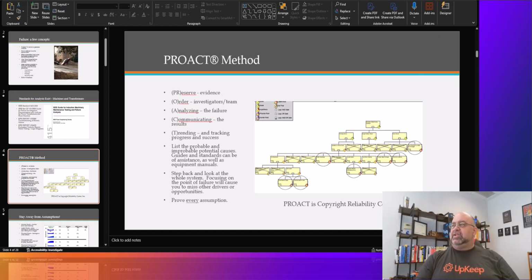So let's get into the incident at hand. This one here, if you've seen it, I call it Motor Go Boom, and you can't see the top of the page, but it is a test that was performed after field testing was performed, in which electrical signature analysis using the EMPATH identified a bunch of conditions. And we went, wow, how is this motor even running? And the vibration guys, because they were doing continuous vibration monitoring, said, what are you talking about? We don't see a problem.